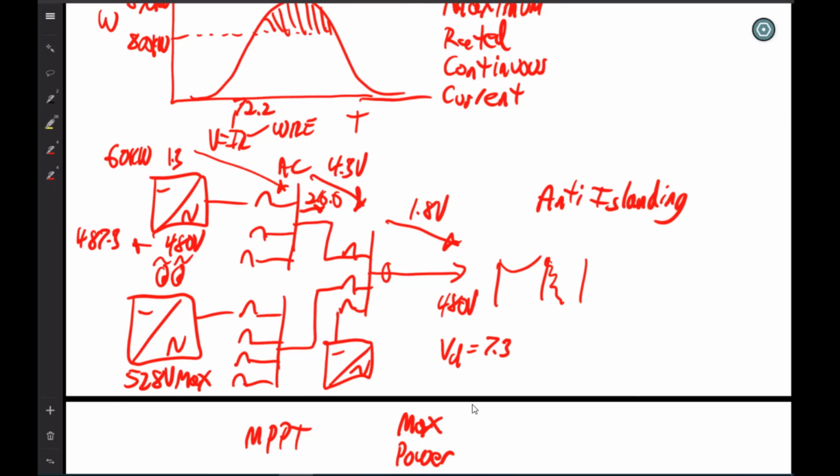It would be creating current and voltage where the utility workers are not expecting any, because they think this side is dead. They think this side still has power, so they want to come up here and grab these and reach it back up, and you can't have power down there. So if you wanted to have backup, you would have to have some way of disconnecting the inverters from the grid, and you could do that with a battery system or an ATS, an automatic transfer switch.